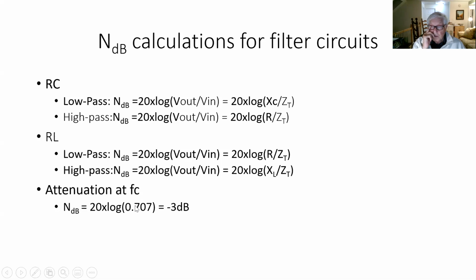And if you recall, that number is the half power unit, 0.707 of your maximum. So 0.707 represents minus 3 dB. If you ever saw a loudness meter used in recording, you'll notice that on the meter itself you've got plus 3 dB and minus 3 dB. The needle goes back and forth so that you can change the loudness to where you want it. You usually want it around the 0 point.